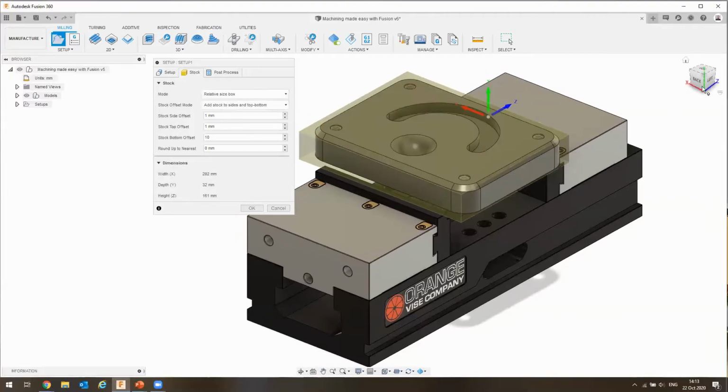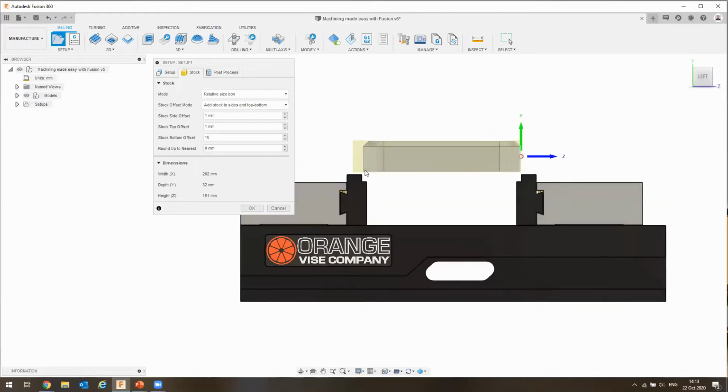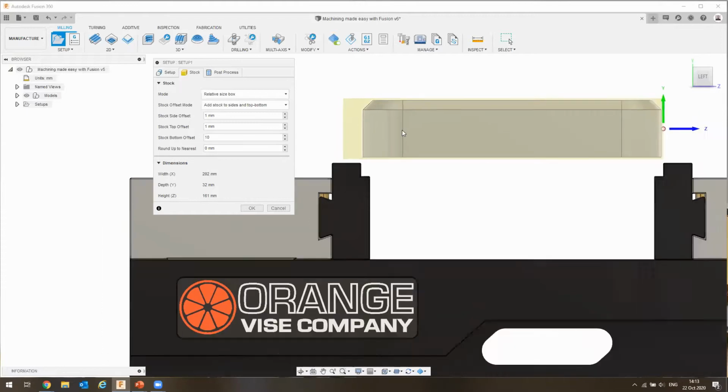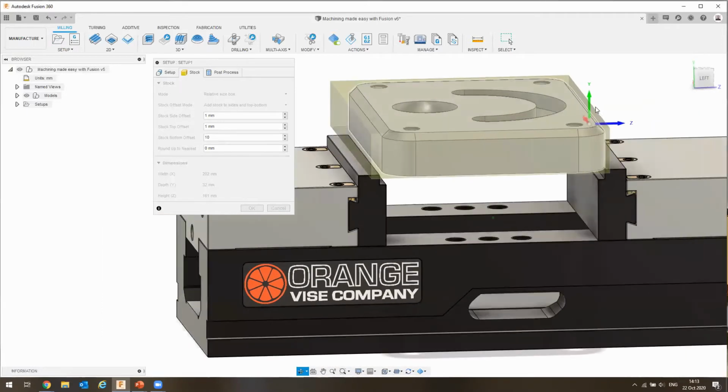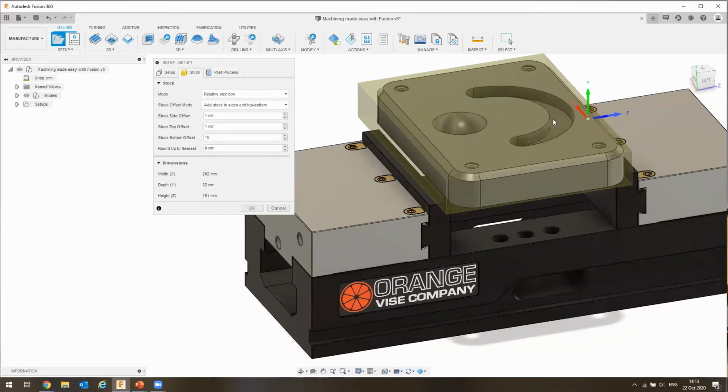And you'll notice if I look from the side, that 10 millimeter has gone over here. And I wanted 10 mil down. I've on purpose positioned this to be 1 mil over and 10 mil down. But it thinks 10 is going this way. That's because of the axis over here, your origin. This is your cutter's position. And right now it thinks Z is going in this direction.